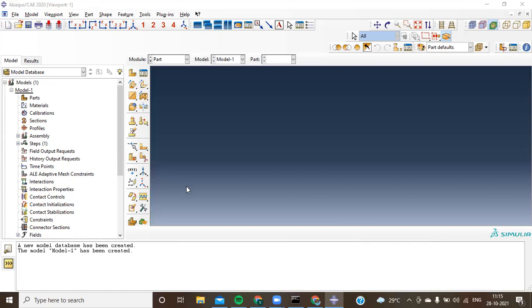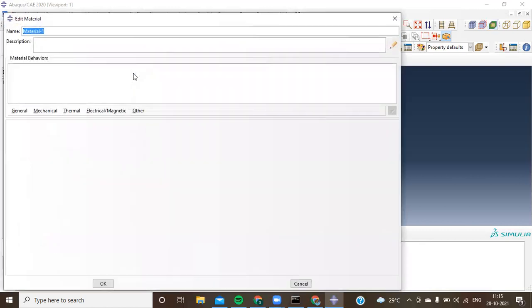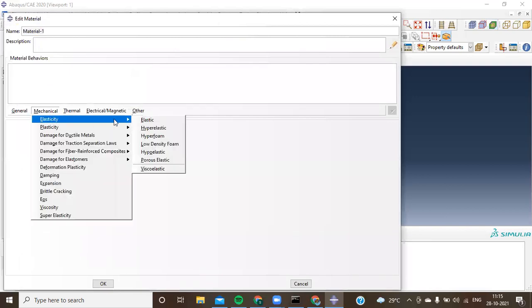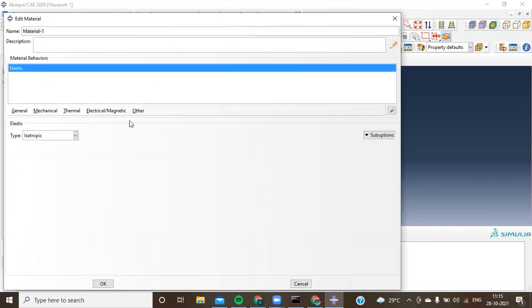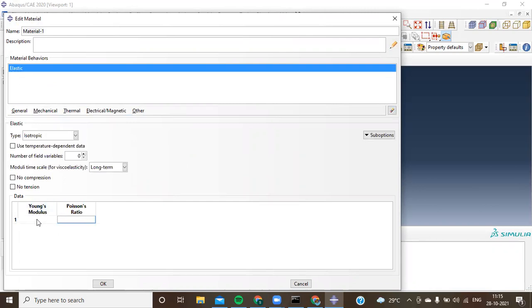It's very simple. See, coming to your question, how to go about the damaged things. When you're defining the material properties, every time you are defining your elasticity, the elastic modulus, Young's modulus and Poisson's ratio. As time goes on, let's say 2 years, 10 years or 20 years, the stiffness of this particular beam has drastically come down. So you have to change this value. You have to identify the reduction value and feed that value so that you can see the difference in the results.